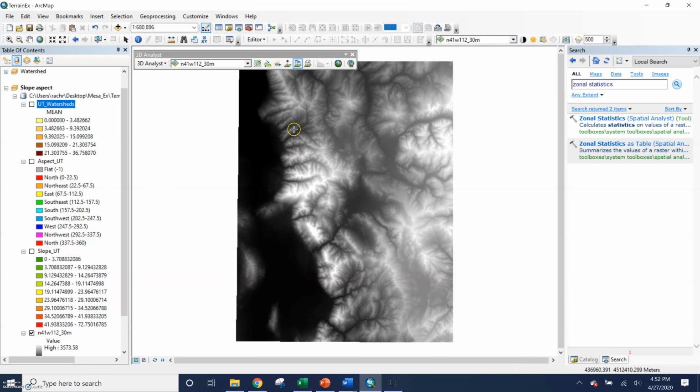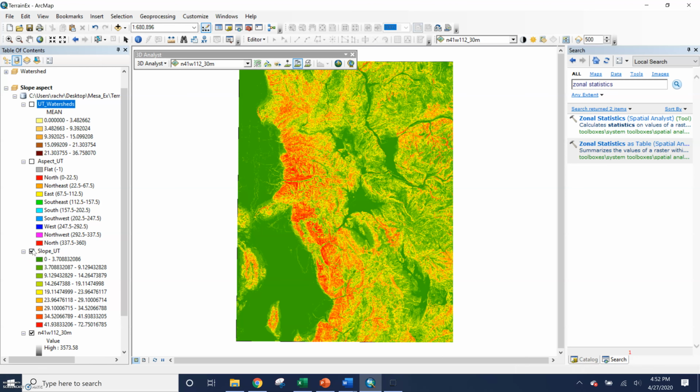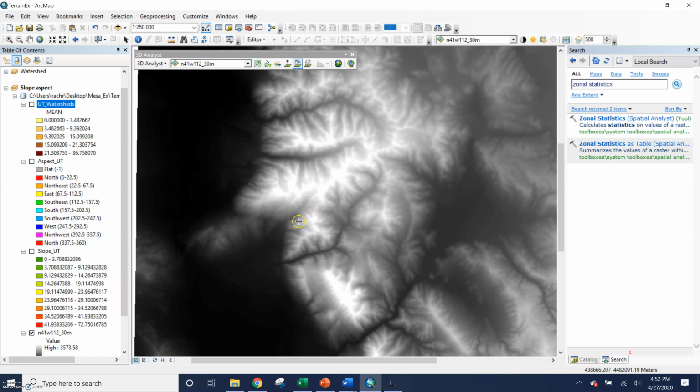And we can start by figuring out, let's see, where's that 70% area? So kind of right there. So we could create our interpolated line, point A to point B. And then we have that line, understanding this is creating where our topographic profile would be. So if we were to cut the Earth in half, this would give us the profile or 3D image of the steepness of the slope. So now that we've interpolated a line, we created a 3D line by interpolating height from the selected surface.